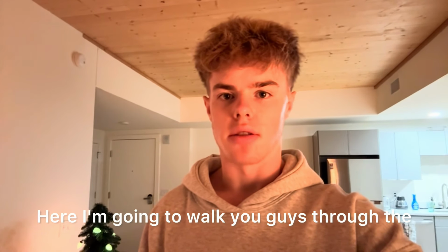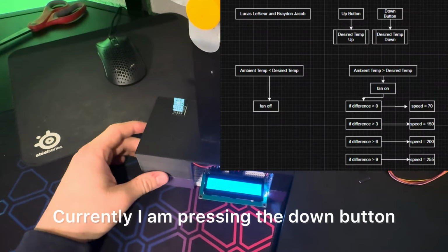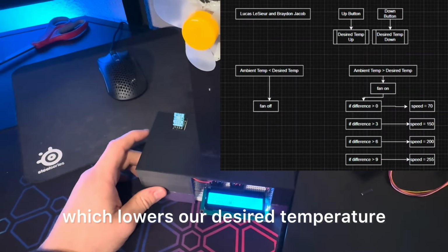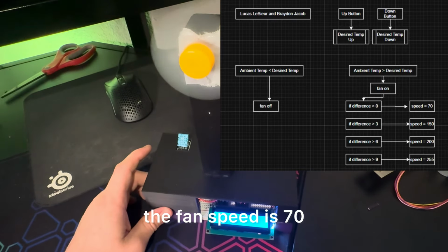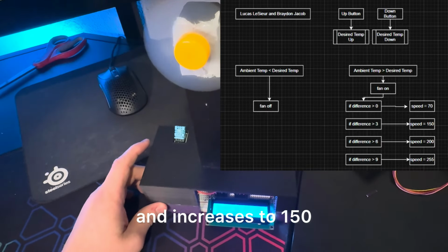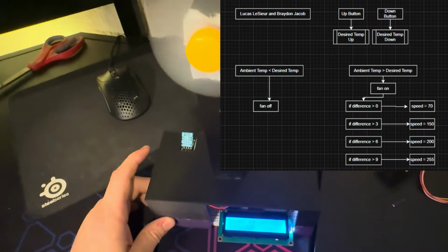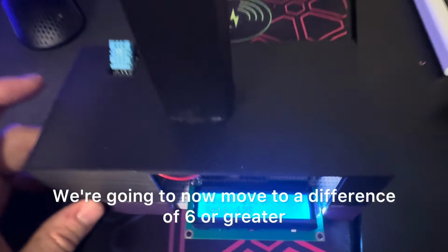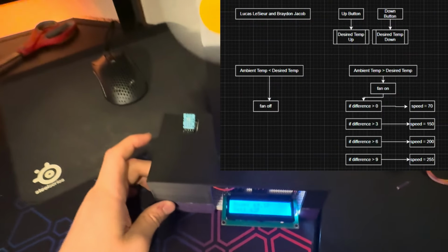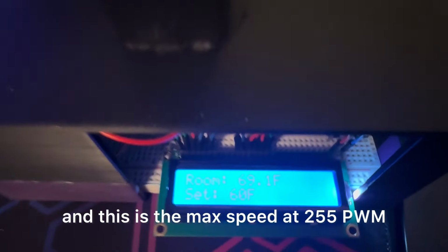Here I'm going to walk you guys through the flow diagram of our system while showing it in full operation. Currently, I am pressing the down button, which lowers our desired temperature. The second that temperature crosses the 0, the fan speed is 70, and increases to 150 when we cross the 3 threshold. We're going to now move to a difference of 6 or greater, which increases to 200. Now moving to 9, and this is the max speed at 255 PWM.